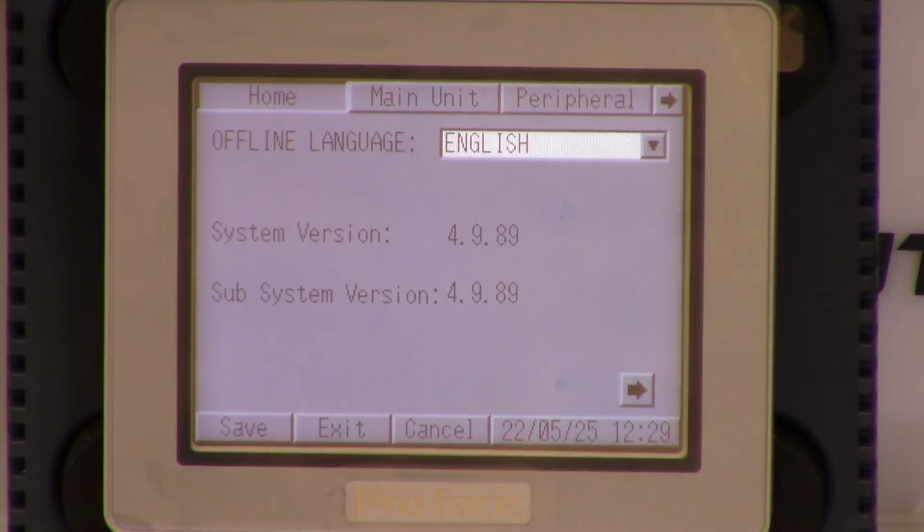If you do that, what we need to make sure is that the network information on the PLC matches the network information on the SCU5 controller, and then the PLC has a distinct IP address compared to the SCU5 controller, and then the PLC also knows the explicit IP address of the SCU5 controller. So in order to check all of these things, what we can do is we can go into the offline mode as shown here.